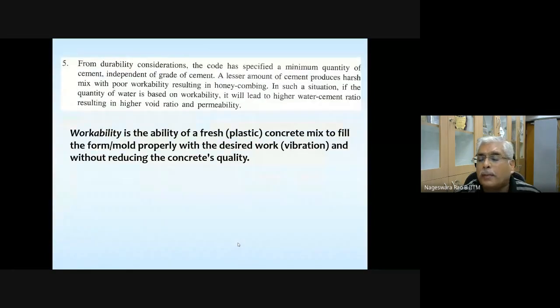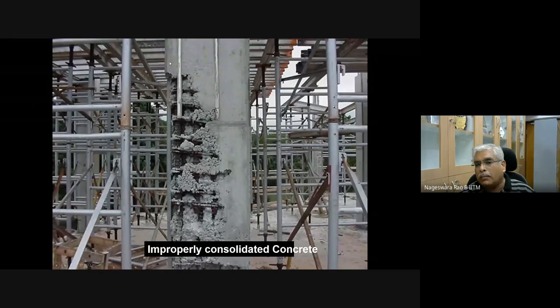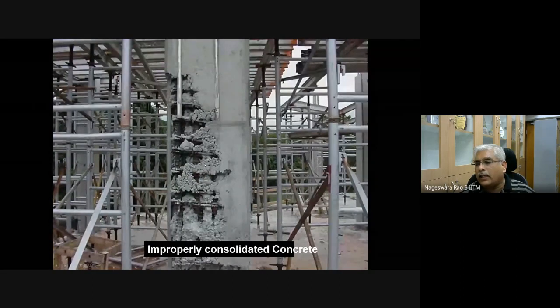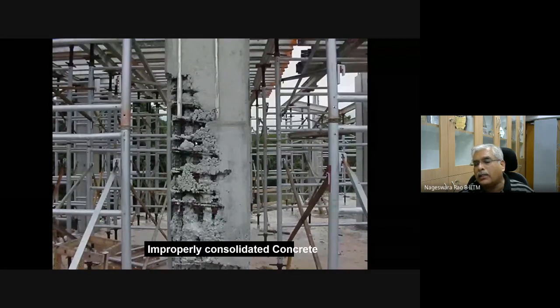So let's see what happens if your concrete does not have enough workability. This is what is going to happen. Please note that at the time of concreting, we will not be able to see this because your mold or formwork is going to be around, and concrete is poured in. The problem is that the concrete adopted does not have enough workability, in the sense that it is not able to flow properly and fill all the gaps. So finally, once it is hardened and the formwork is removed, this is the result of it.